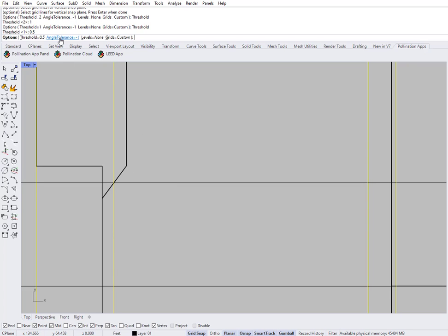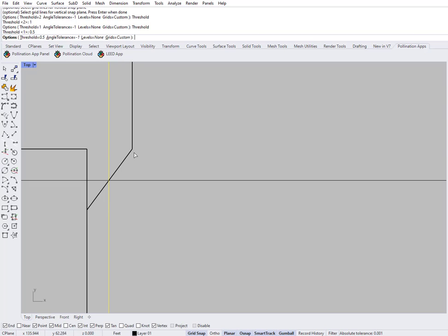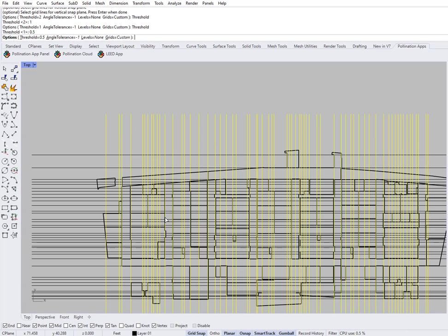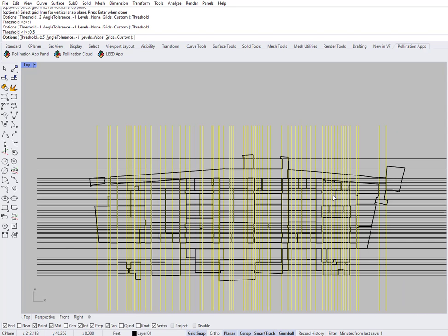If you set it to a number, for example, if I say 5, it means only match if the difference of the angle between this line and the guideline is less than 5 degrees. So in this case, it's about 40 degrees, so it won't match. If I set it to -1, then it ignores it. For now, I'm going to set it to -1, so it ignores all the angle differences because I don't see any major issues happening.